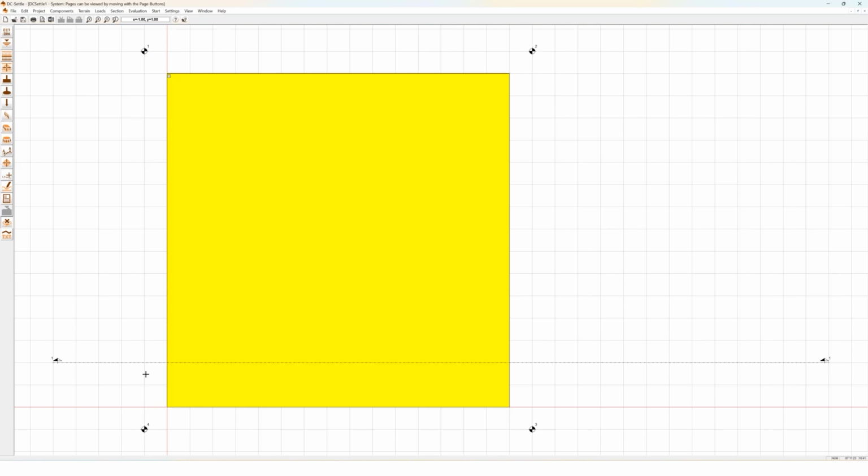When we say we have a greater silt layer thickness on the left side, and a really small layer thickness of silt at the right side, then it will interpolate between all the bore points, and we have different layer thickness all over the area. And this leads to a different settlement, of course, and then we can see the layer thickness later in the section.